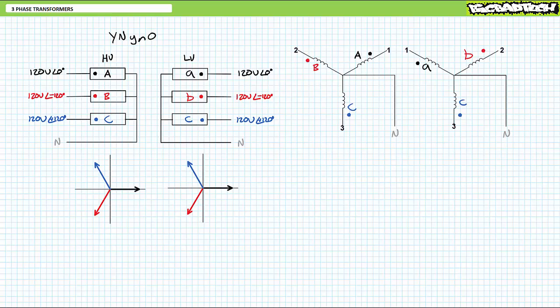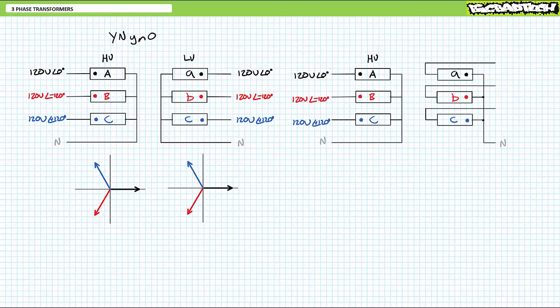Given the numerous terminals available on a three-phase transformer, a YN-YN0 configuration is just one of many possible configurations. Consider this subtle modification and its important consequences. Rather than tying together the non-dotted ends of the low-voltage secondary windings, let's instead tie together the dotted ends and use them as the central node of a Y-configured output, effectively using each low-voltage secondary winding backwards or inverted.